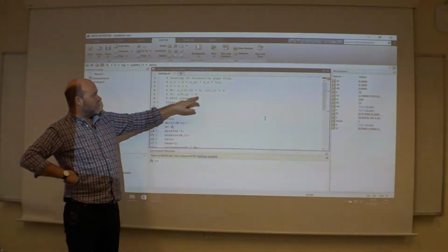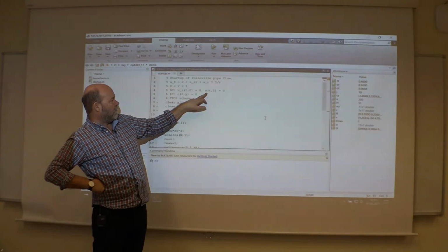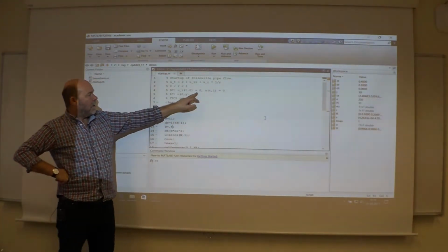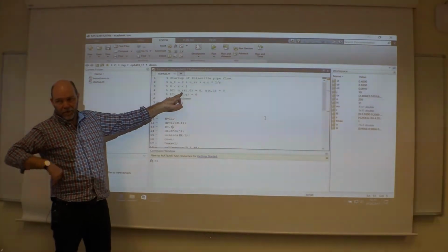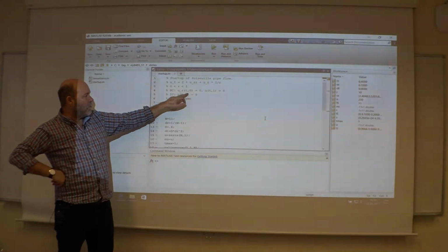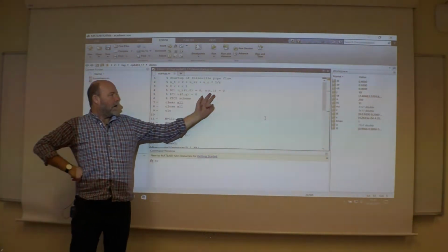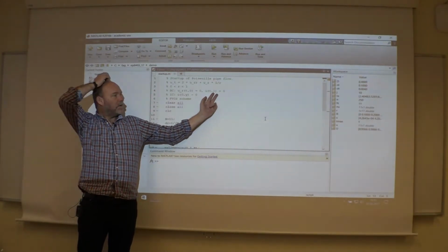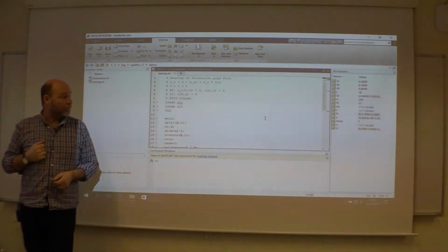Boundary conditions, you have the 0 on the wall for all times. And in the center, the r derivative, the velocity gradient, should be 0. So I use then a Dirichlet condition on the surface, on the pipe wall, and I use a Neumann condition in the center.